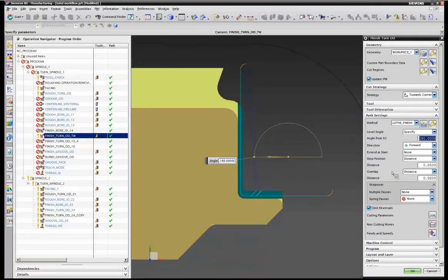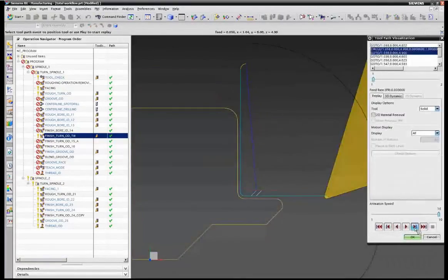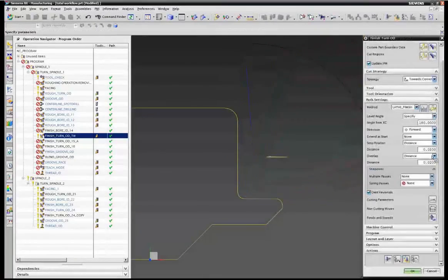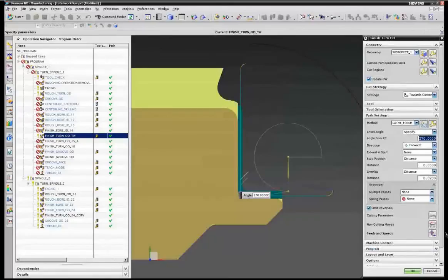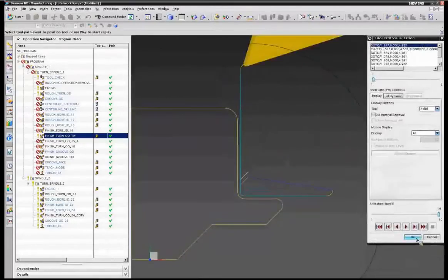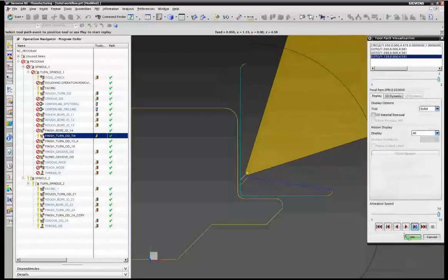In this case, the first cut has been selected to be the diameter followed by the faces; you always have the ability to switch those by redefining the angle, in which case also the stop position will be updated. So you now notice that it's on the face.